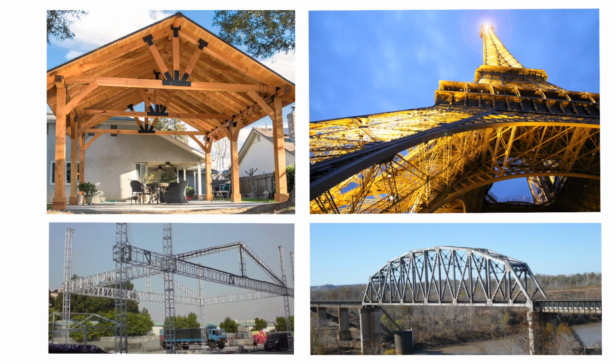And the trick here for this truss system is probably clearest if we look at this bridge. Remember that we have a smiling beam. If the train drives over this bridge here, then this part wants to move down. And remember that we said if the beam is smiling, then we have tension on the bottom, compression on the top.